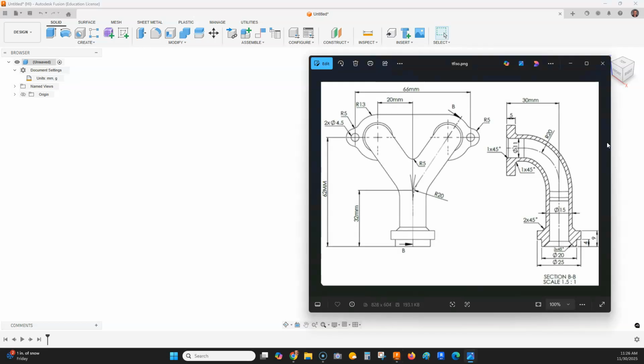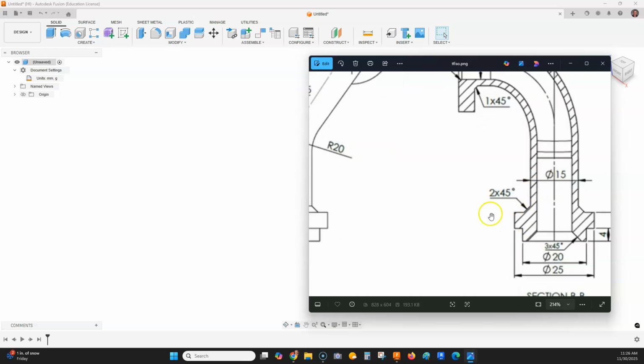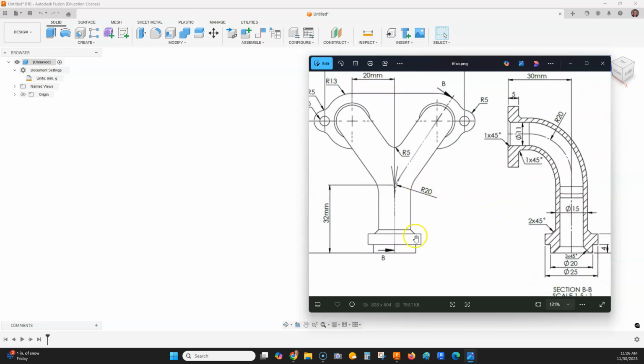Now let's take a look at that two-dimensional drawing. We have this cylinder base that has a height of 32 millimeters, and I can also tell that there is hollow in the middle because I can see section lines right here where material was cut. And over here in our front view, I can see a center line that comes up to here and then turns and goes on an angle, where I can see the letter B, and these arrows show me where the material was cut.